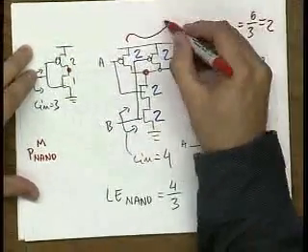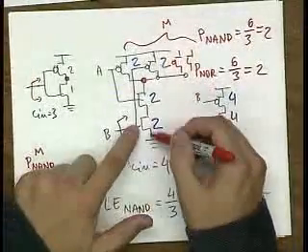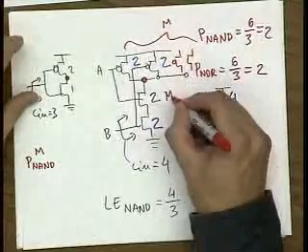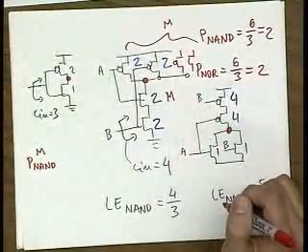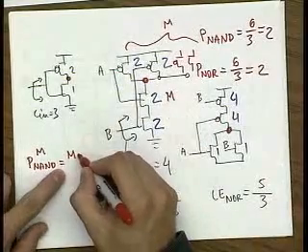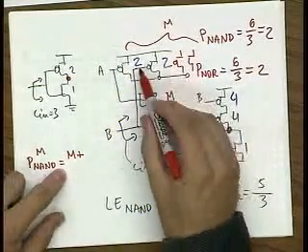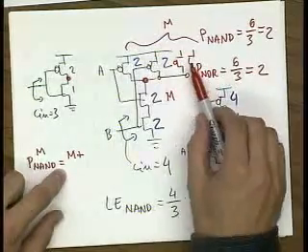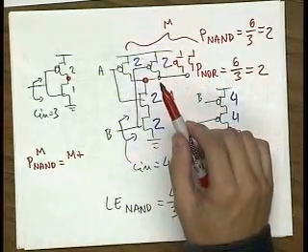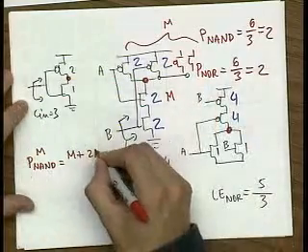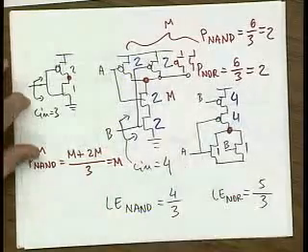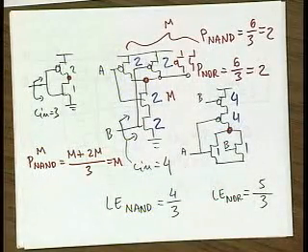So you have M of these in parallel, and then since you have a stack of M transistors, each transistor has to be upsized by a factor of M, right? So the total is equal to M, plus you have 2 times M, because all of these PMOSs are width 2. So you have 2 times M divided by 3, so the parasitic of this gate is equal to M, right?